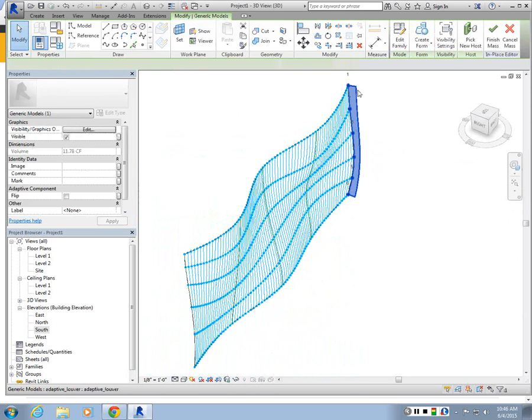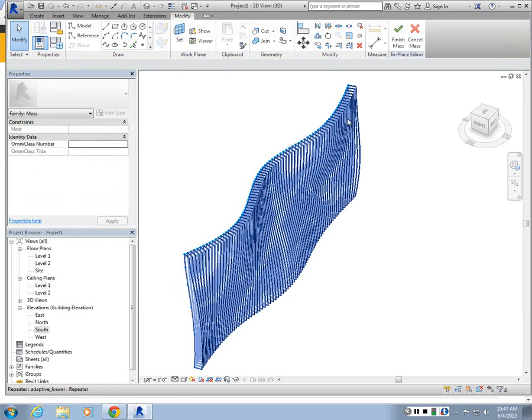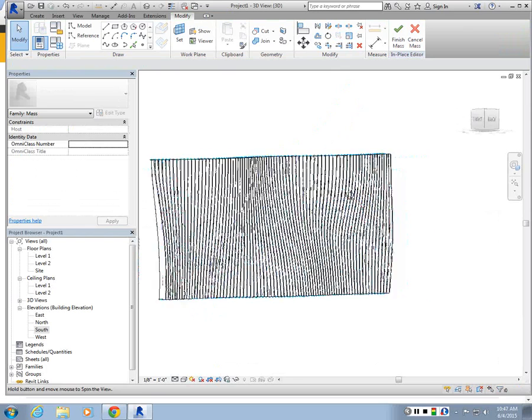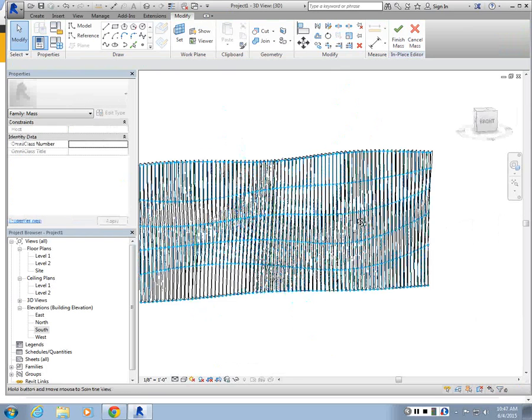You can then choose the component and you can come to the modify option. There is this repeat tool. And if you press that, it will just repeat the same process to all the control points. So it should do vertical louvers along this line. However, if I had 60 divisions, I'll get 60 points. So now I have my louvers placed.